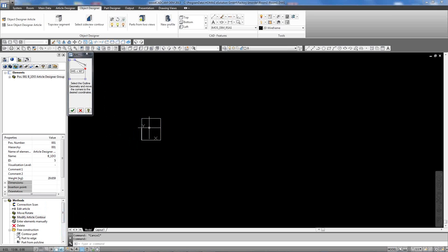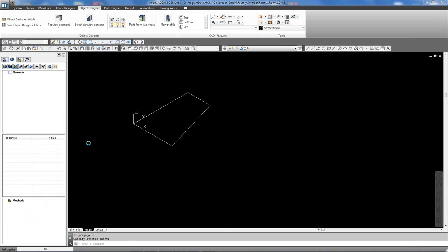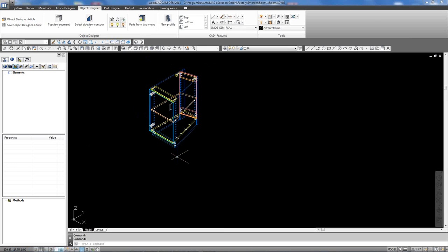So I hit that, and you see that my cabinet kind of goes away, and now I can choose the grips here, and I can basically change the shape of my cabinet and get some funky looking cabinet like that just by changing the contour of a standard library item. Nice. Okay. No formulas, no variables. It just does, yeah, it.